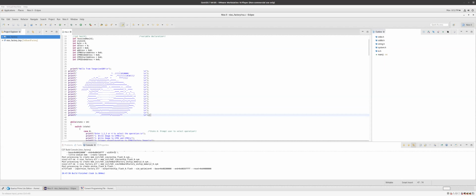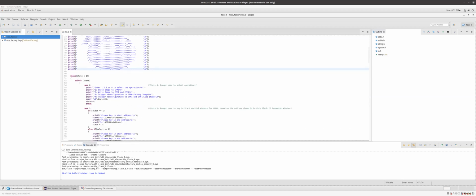I'm using the USB interface on the development board to download and run my NEOS programs. That looks like a serial port to the computer, right? Yes, but there's a port marked UART, which is not the one to use. There's a port with an identical connector marked USB, which is the one that you should use. So the UART one just goes to a couple pins on the FPGA and you have to write your own? Yeah, I think that goes to the two specified pins.